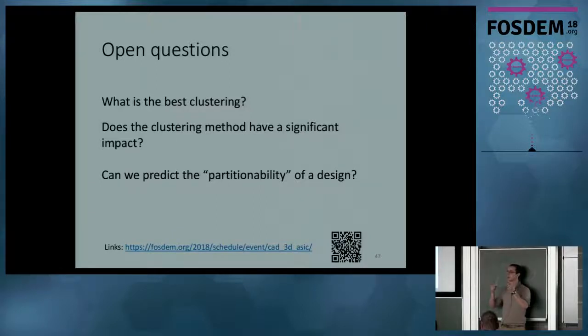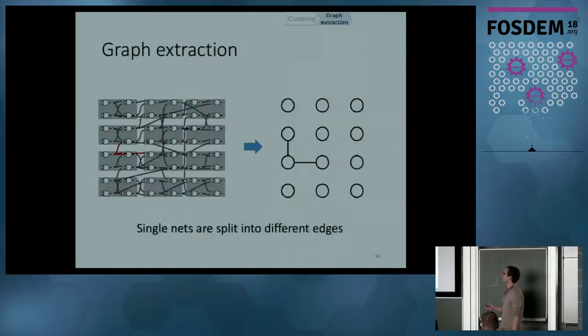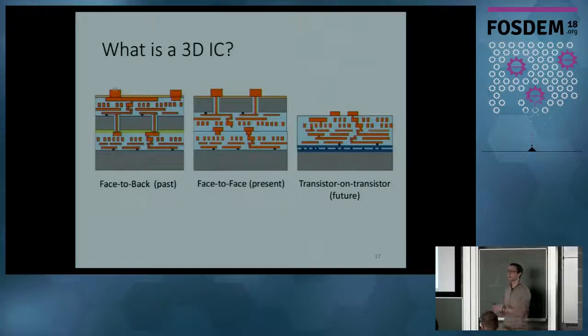Yes, actually, so indeed, if I just go back to the slides, it would be easier for everybody to understand. When you go in 3D, you have obviously interconnection between the 2 layers, like here. And those interconnections are longer than the regular metal layers. So the one you have here at the front is longer than the metal layers you have here. And we try to reduce the performance loss due to this longer via interconnection between 2 layers by cutting the longest nets, that would be shorter even when going 3D. So you would have performance loss if you cut really short wires that would be elongated by going 3D, and we try to avoid that.